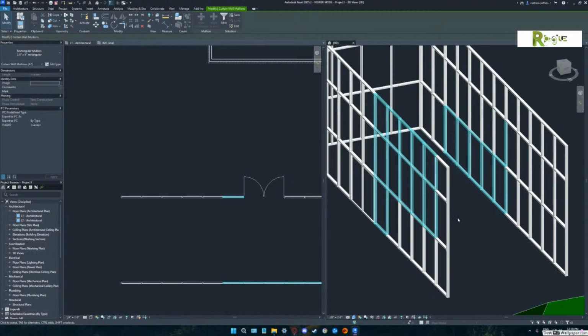And if you wanted to, let's go see in properties, see if there's another type of mullion in there that you could change it to. I don't know if they've loaded any. Yep, hit that arrow. It won't let me click anything. All right, the reason it won't let you click it is, you don't know it from the back panel, but some of those objects are still pinned. Yeah, that's right, but don't do anything because I don't want you to lose this. Some of those objects are still pinned. That's why it won't let you change them.